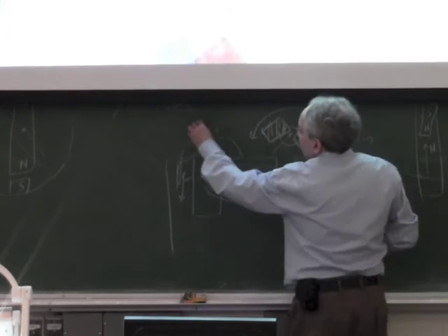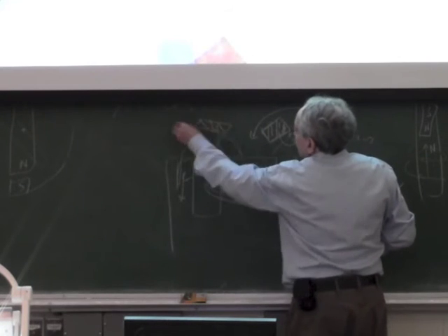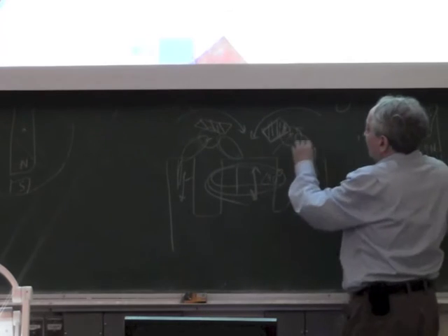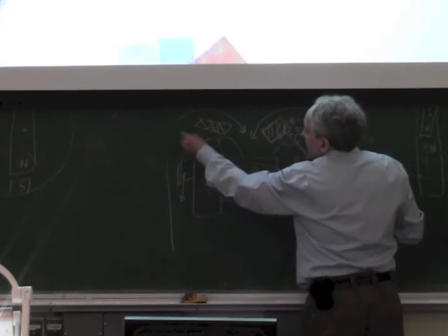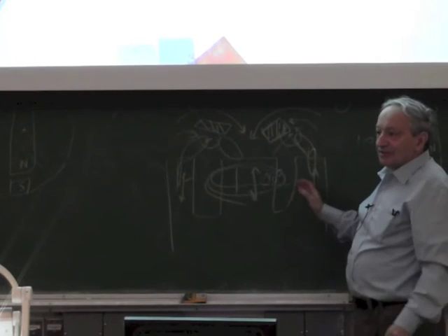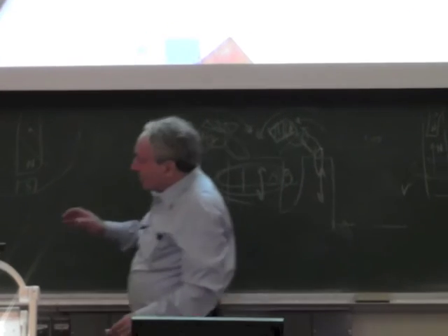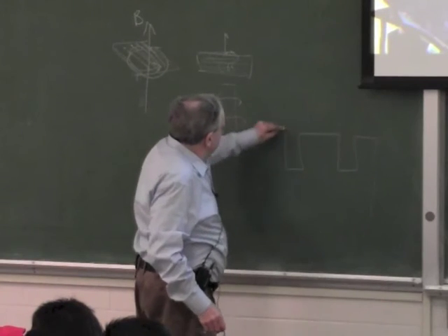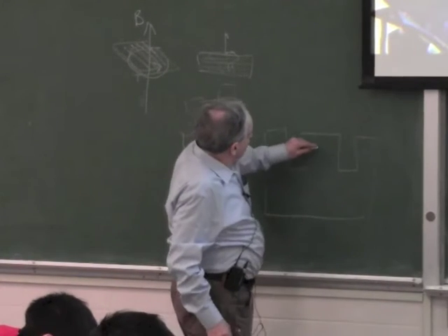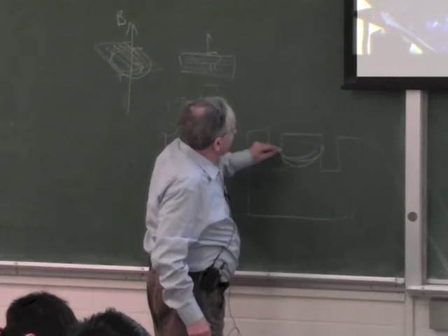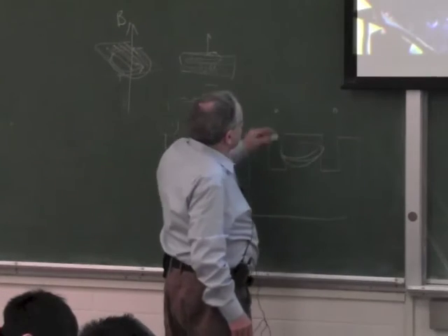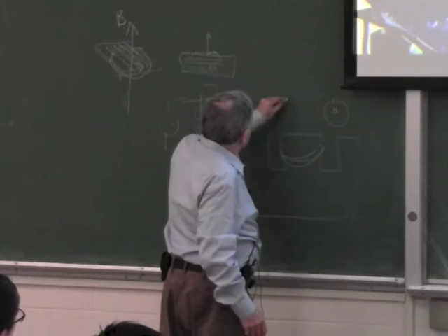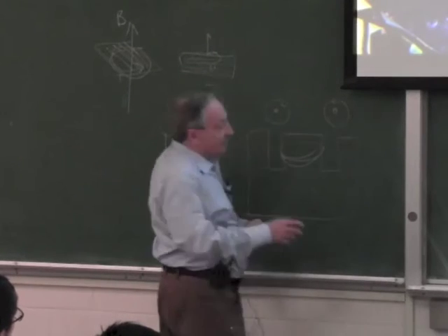If I put a piece of conductor on this side, it's going to try to rotate with the field this way, because this is symmetric. If one field goes this way, the other field goes this way. Okay, so now we're coming to the end of the mystery. If I have this shape and this short-circuiting coil, we know there are at least 2 points where this is a true rotating field, and there are many points where it's not truly rotating, but it's closed.